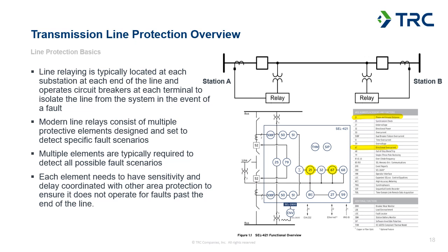So generally, when we're doing line protection, we're relying on phase and ground distance elements, the 21 that I have highlighted there, as well as directional overcurrent. That's generally directional ground overcurrent protection. And we'd have multiple levels and different schemes we'd apply using those. And we'll talk a little bit tomorrow about the reasons why we select those schemes and how those elements are set, and that's some of the stuff we'll be covering over the next couple of days.